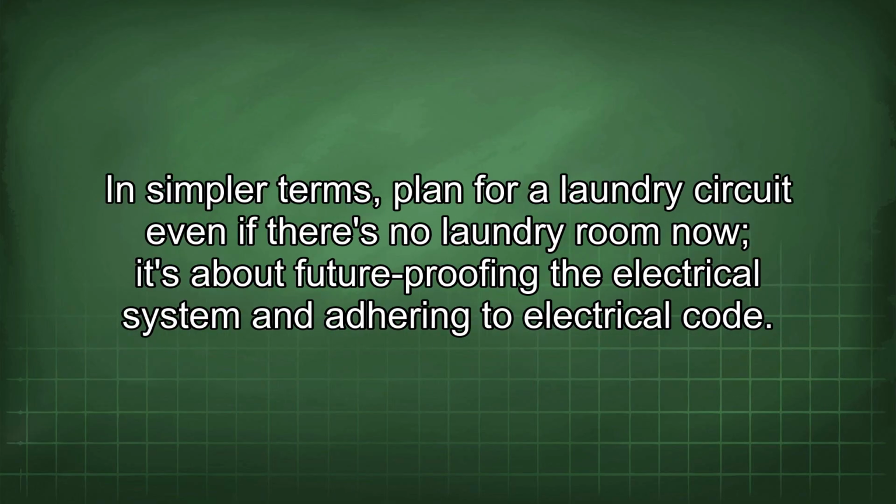In simpler terms, plan for a laundry circuit even if there's no laundry room now. It's about future-proofing the electrical system and adhering to electrical code.